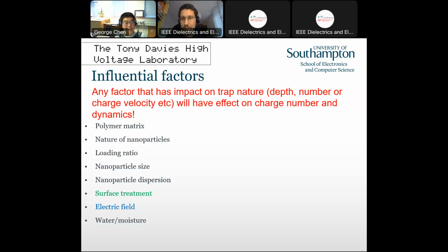However, you must bear in mind that you don't want to produce a very high field in the system, which could lead to aging and also failure of the capacitor. So there's a limit you can go. And one thing I didn't mention earlier is that for electric applications, we want to have more charge in the system, and so that's beneficial in that case.